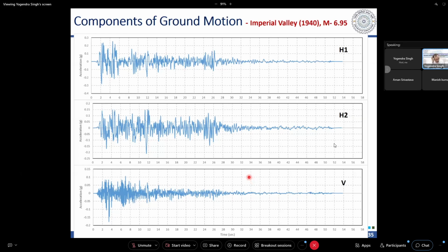So when we are using time history, sometimes we use artificial time history. And what people do, if they have to perform biaxial analysis under two ground motions, is apply whatever is given in the X direction in the Y direction as well. That should not be done. The ground motions are naturally uncorrelated, and the ground motion in H1 should be uncorrelated with H2, and it should be uncorrelated with V, the vertical component. The same ground motion scaled by different factors cannot or should not be used. That will give highly conservative results.